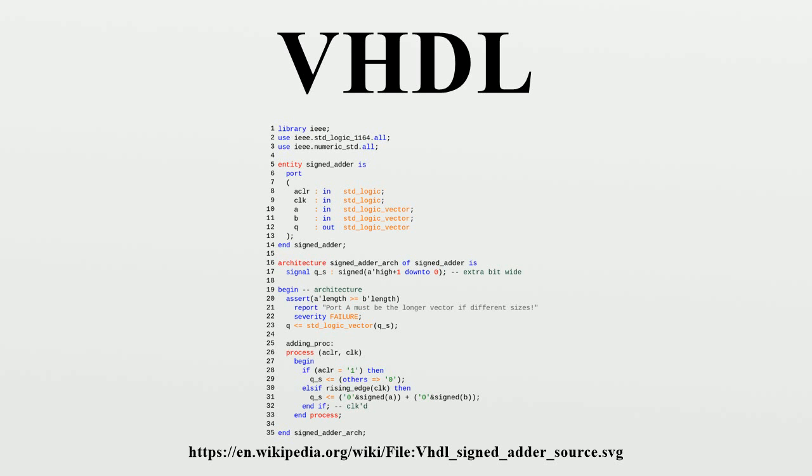Simulation-only constructs. A large subset of VHDL cannot be translated into hardware. This subset is known as the non-synthesizable or the simulation-only subset of VHDL and can only be used for prototyping, simulation and debugging. For example, the following code will generate a clock with a frequency of 50 MHz. It can, for example, be used to drive a clock input in a design during simulation. It is, however, a simulation-only construct and cannot be implemented in hardware. In actual hardware, the clock is generated externally. It can be scaled down internally by user logic or dedicated hardware.